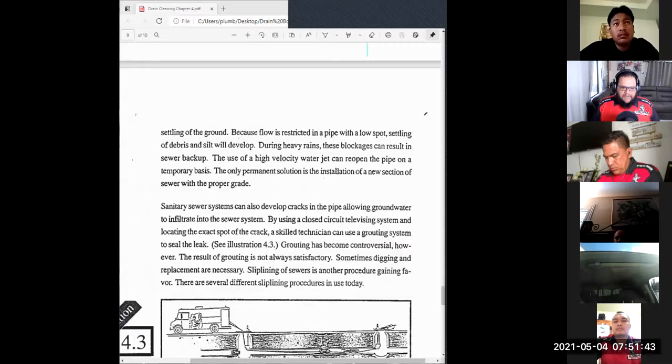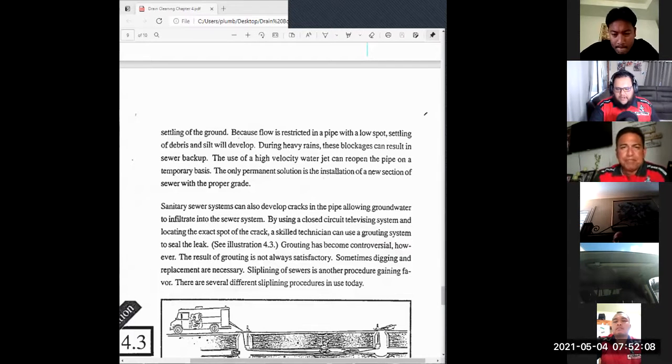And then also bedding the pipe, making sure that the ground is compacted under the drain, always using your level as you're moving down the drain. As you lock in your 1/4 inch, secure that pipe, bury that section, and then just keep moving back on yourself. Because if you have to keep chasing your grade back and forth, you're going to have to keep digging it up, moving dirt.